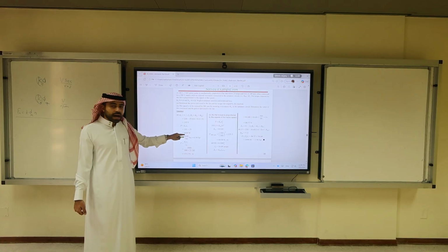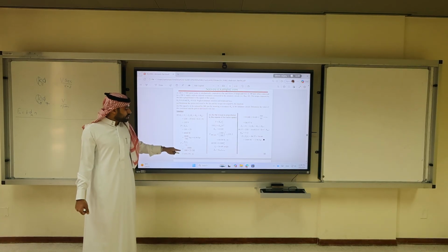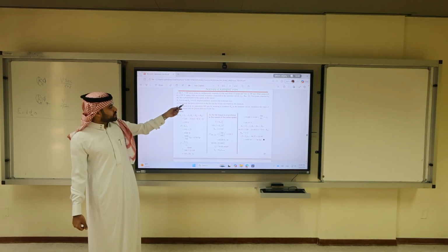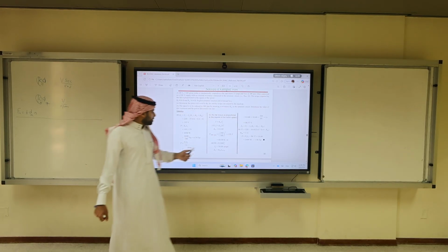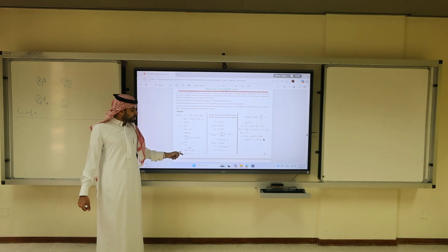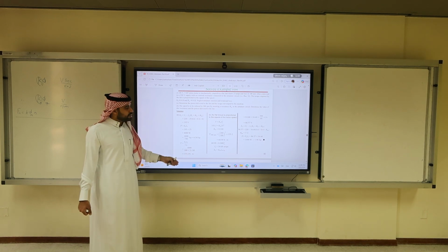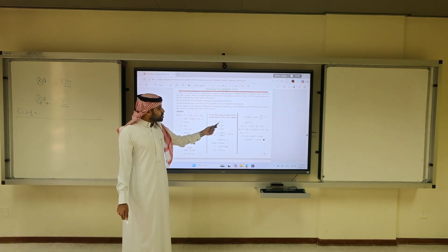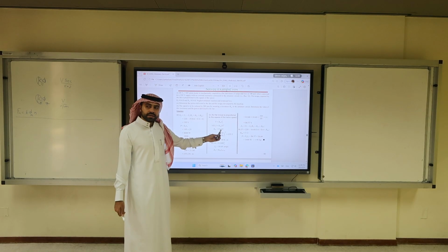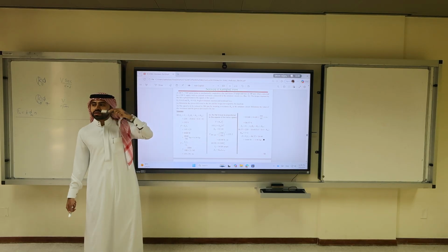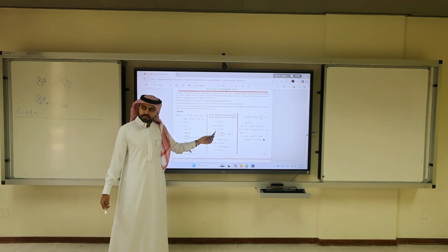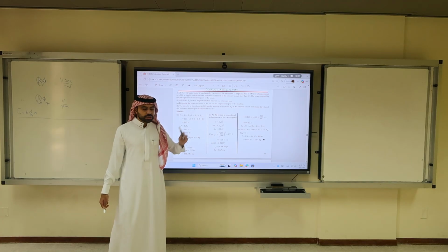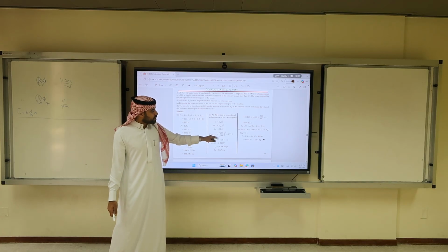From the power, you get the torque by dividing by omega, which is operated at, I think, 300 RPM. So convert 300 by 2 pi over 60, and the torque is 155.2 Newton meter. This is part A. In part B, you have to calculate the constant KSR. One way to calculate it is through the torque. Torque over IA squared is 0.248. Now, if you change the motor speed, will KSR change? No. The torque will change. The torque is according to this equation.